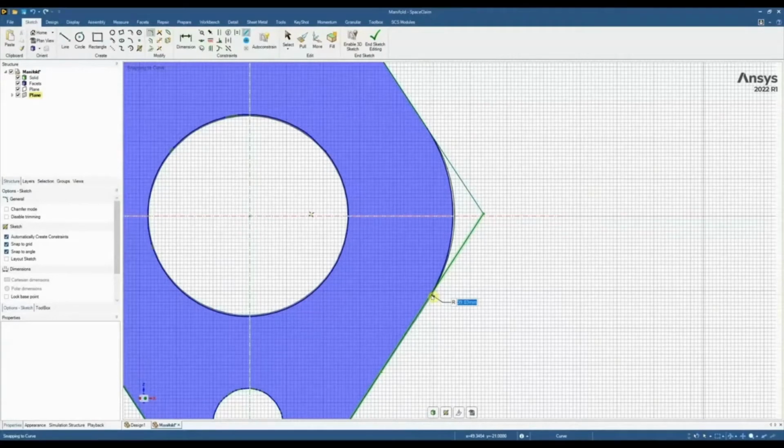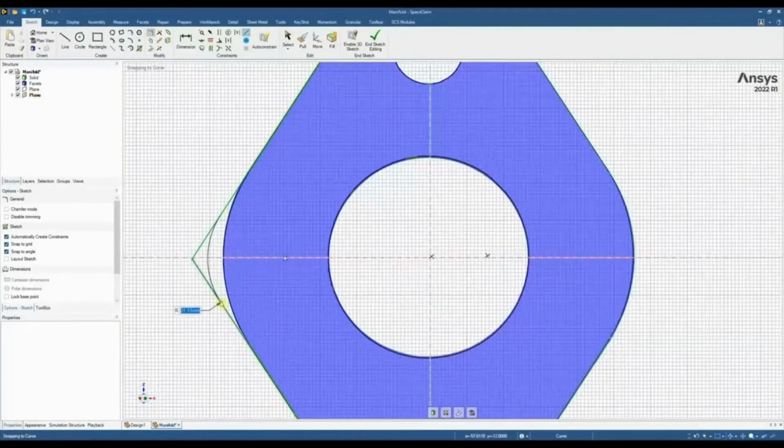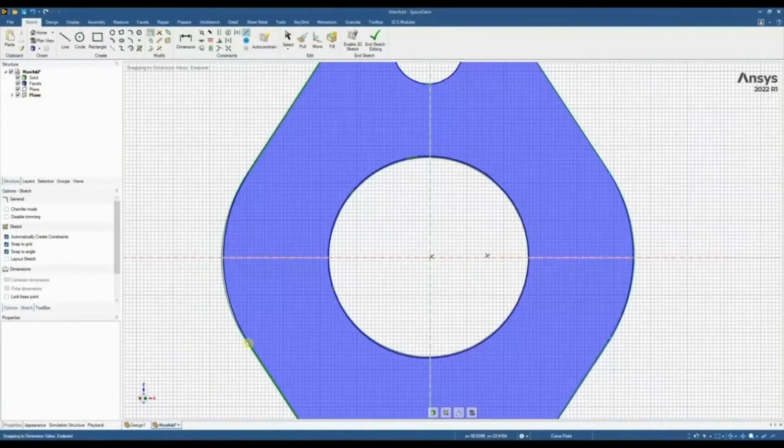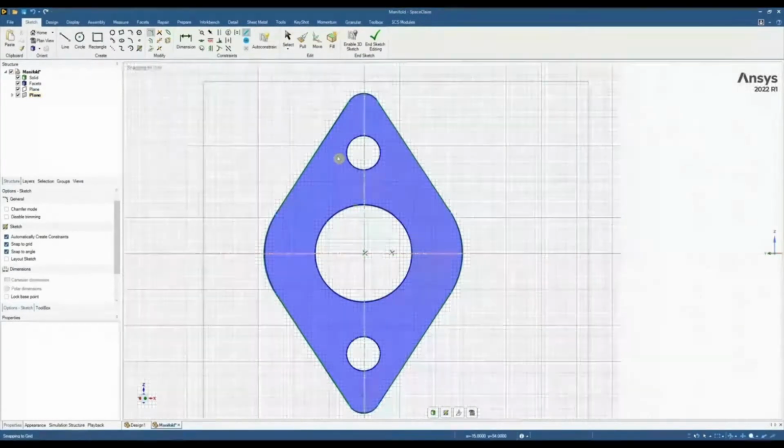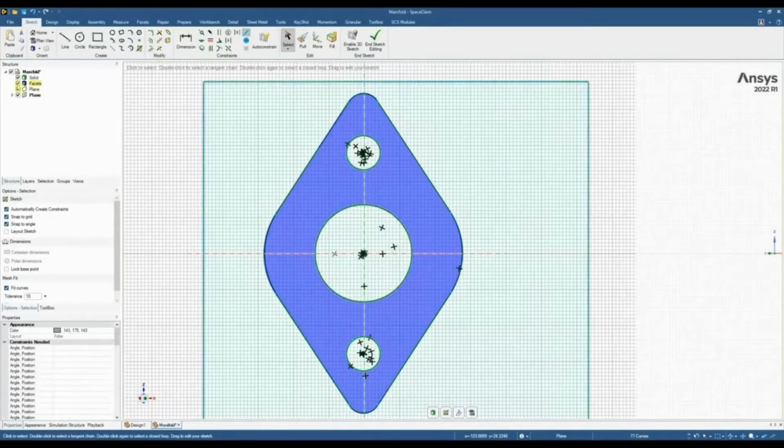So we can see here we're probably looking at around 40, and we'll do the same on the other side. So this is a slightly different way of doing it. This is probably the way I'd do it realistically, because you're getting a lot more control. Rather than spend loads of time on these areas, I'm just going to copy and paste them and do the repair curves.